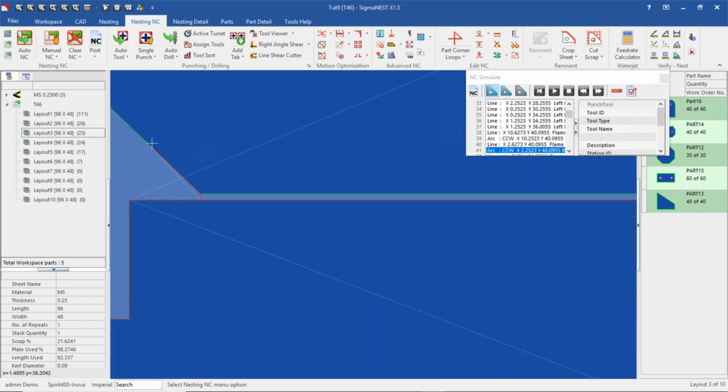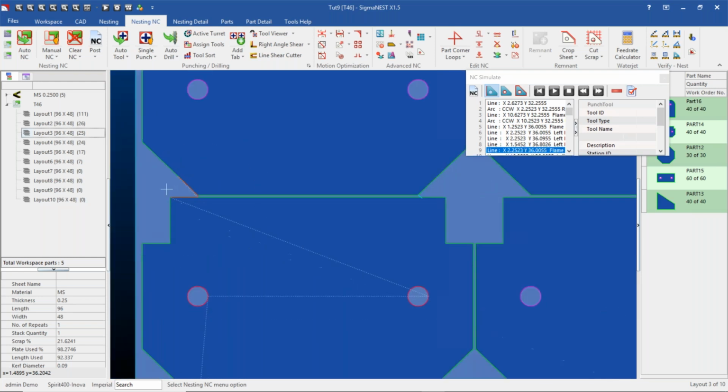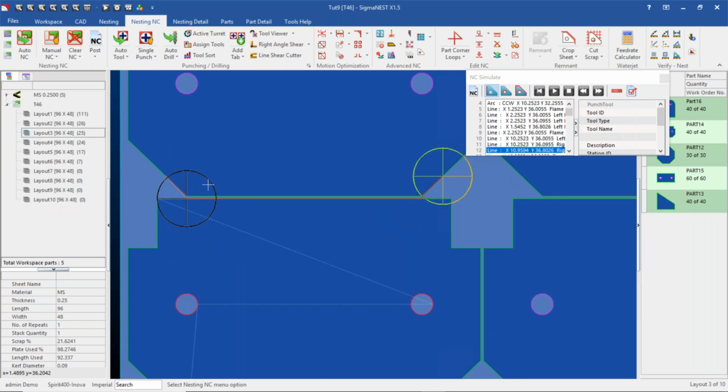a prep cut right here. If I back it up, it's starting from the edge, goes to the common cut area, but instead of going through the common cut, it goes through the next part, throws in the prep cut into the other part, and we'll do that on the other side also, where it extends the prep cut into the other part, finishes off that part, and then when it cuts the next part next to it, right there is when it cuts the next part, the pickup point is now starting at that prep cut, which is approximately 1 inch away.